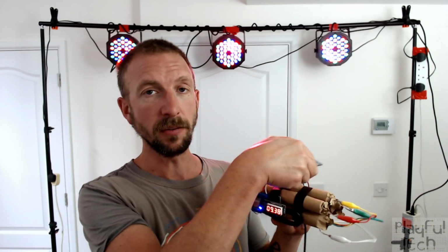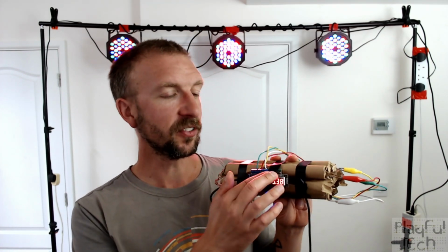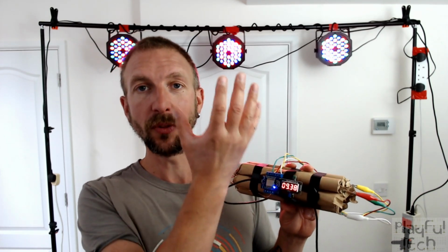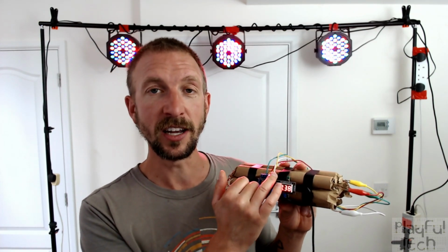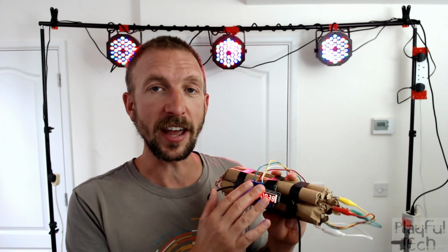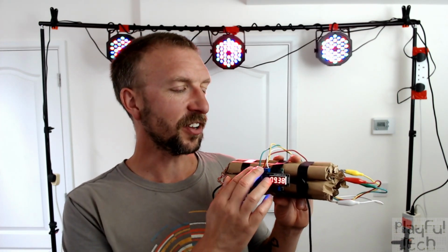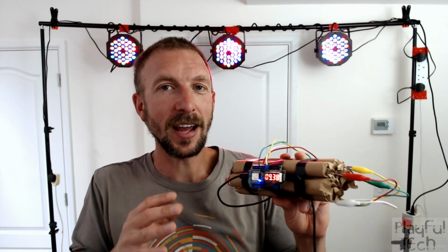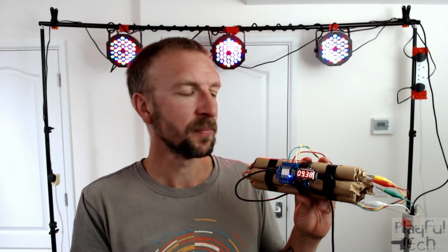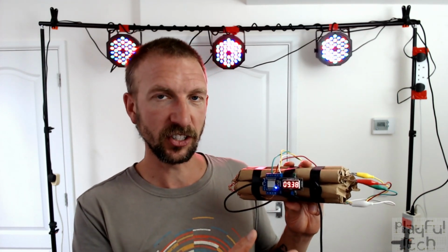When you cut them, or when you pull them out, that circuit is broken, and what happens instead is that the pull-up resistor on the board will pull that signal up to a high voltage level, and these will suddenly read high. In the code, that's what we use to detect whether any of these wires have been cut or not. Now that's fine, but like I said, with some of these input pins, pins 3 and 4 on the Wemos Mini, you can't have them pulled low and get it to start up. So I had to be a little bit careful about selecting which pins are used for which function here.